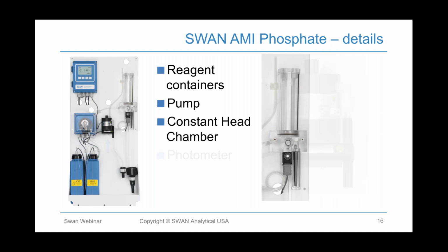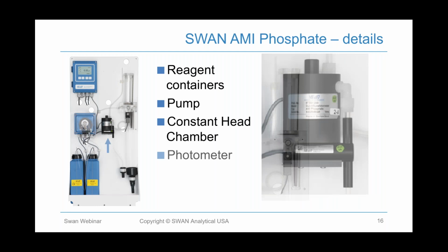And then there's a close-up of the photometer, and you can see there on the bottom, that piece on the bottom is actually a bubble detector. So that's how we are measuring that the instrument has flow. And should this instrument ever lose flow, the instrument will alarm. That can be output to a SCADA system to show that the instrument has flow or does not, and we'll stop pumping reagents. So no more the instrument loses flow and we continue to chug a bunch of reagents through there and gunk up the inside of the analyzer and waste money on chemicals that we're not using.